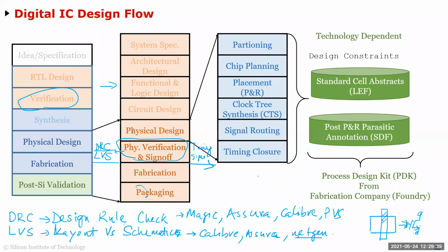Then it has the .lib files, which have all the timing data, and then it creates what's called the SDF and other post-layout data, which is essentially extracting the parasitics. Like in a full custom design, it'll extract the parasitics as pure capacitance, from this node to that node. If you use this data, you'll never be able to finish timing closure.